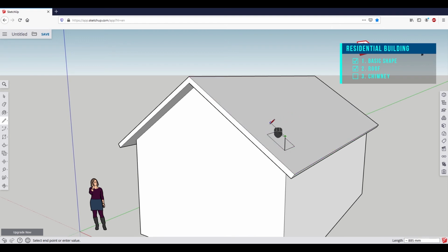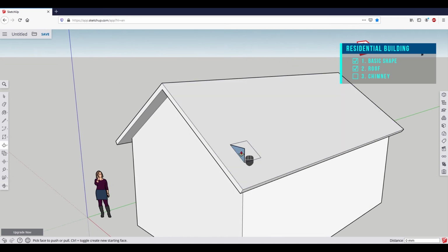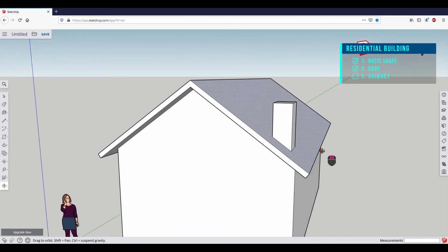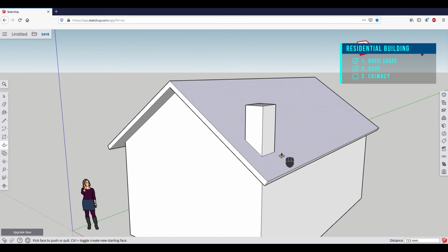Now we have to complete the connection with another left click, and then we can select the push-pull tool and extrude the surface to this corner. Now extrude the height, and that's it. This method is better than the first one, but still, there is room for improvement. Let's see how the pro does it.